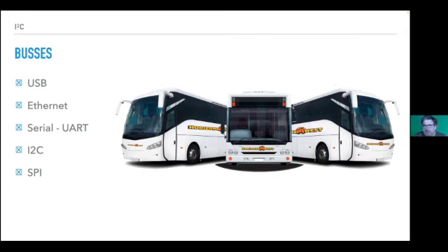So the difference between I2C and SPI is that with SPI, you have 4 wires from your computer to your device. So you have one that sends data one way and one that sends data the other way, like serial also, like USB. Data on one pin one way and data another way on another pin. But because they want to talk very fast compared to, for example, serial, they then have a third pin, which is a clock that simply, from the computer, goes up and down.